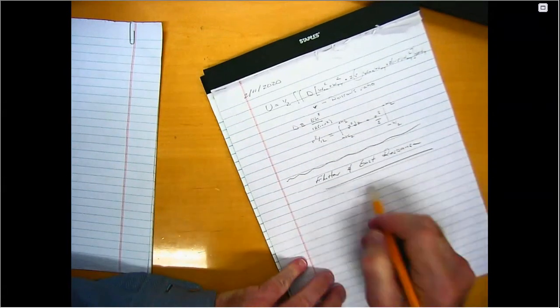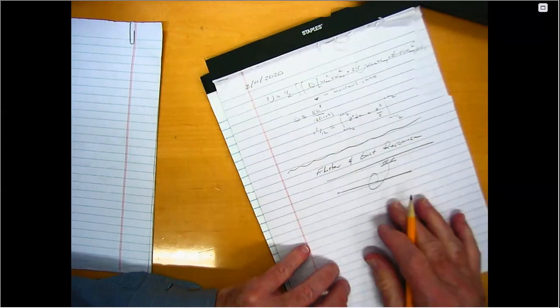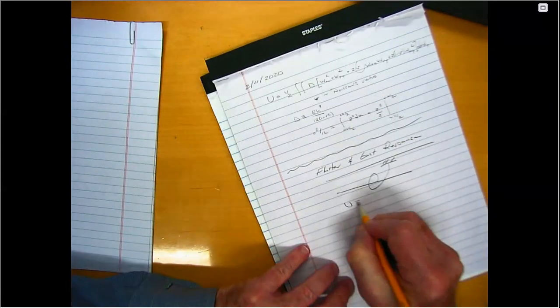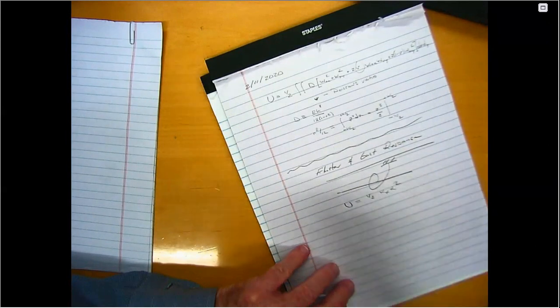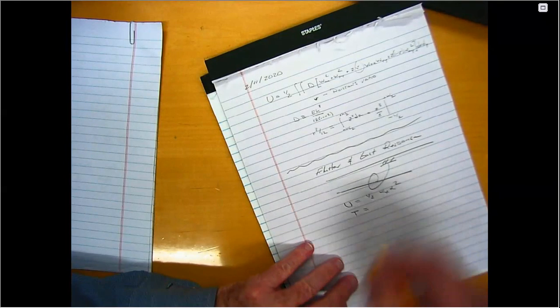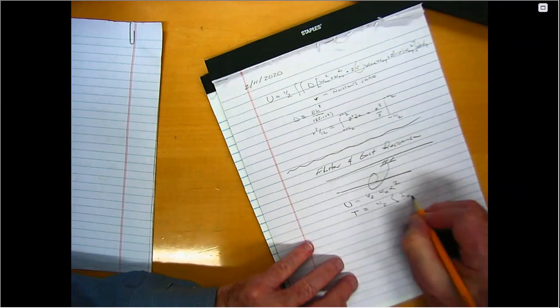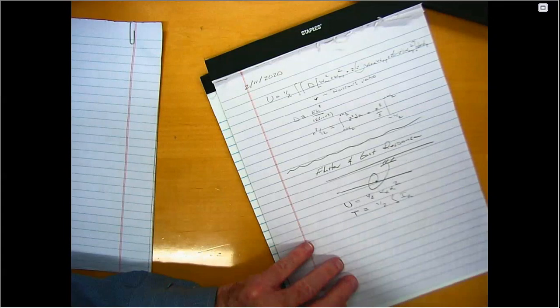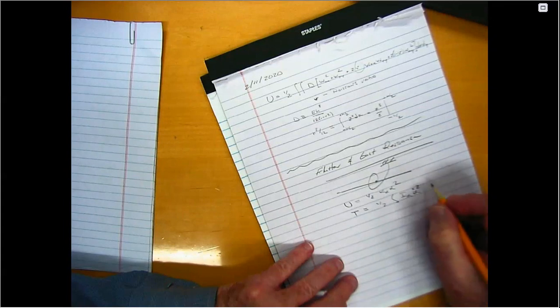Our typical section model is this model with the torsional spring. And so the potential energy is still 1/2 k alpha squared. And I suggested that the kinetic energy could be written as 1/2 the moment of inertia about this axis times alpha dot squared.